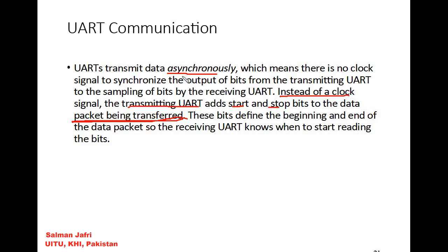So UARTs can transmit data asynchronously, which means there is no clock signal to synchronize the output of bits. Instead of a clock signal, the transmitting UART adds start and stop bits to the data packet being transferred. These bits define the beginning and end of the data packet, so the receiving UART knows when to start reading the bits. So all synchronization is done by using the start and the stop bits, right?